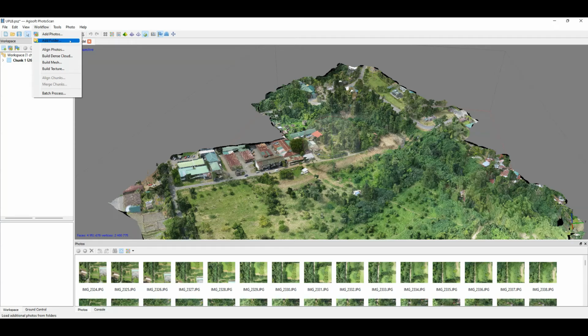And again, the images should be taken from the same height of the UAV so that the images will be regular. And there should be an overlap of the image of around 40, 50, 60, 70, or even 80% to get the best image.